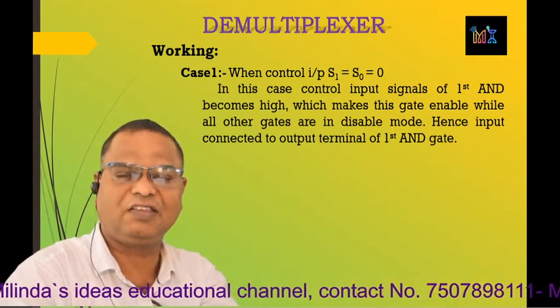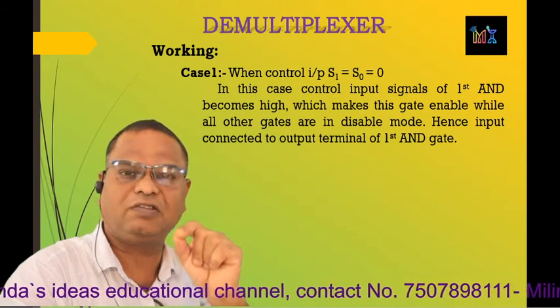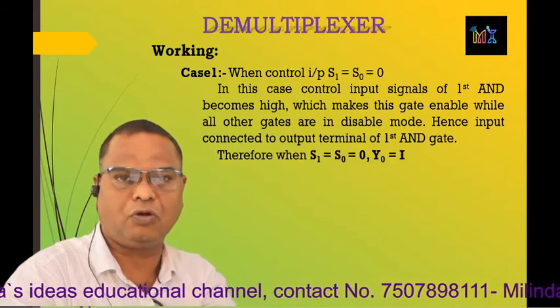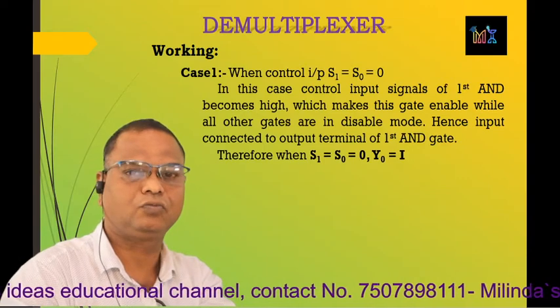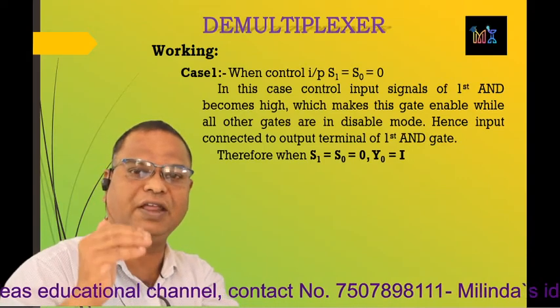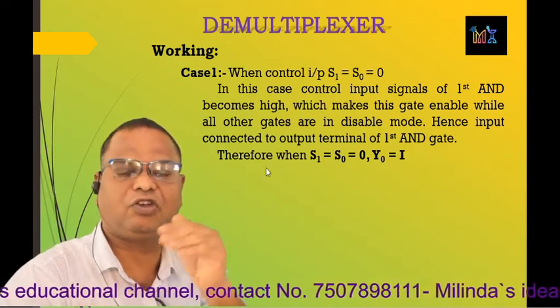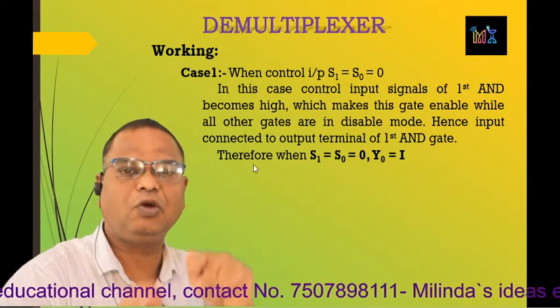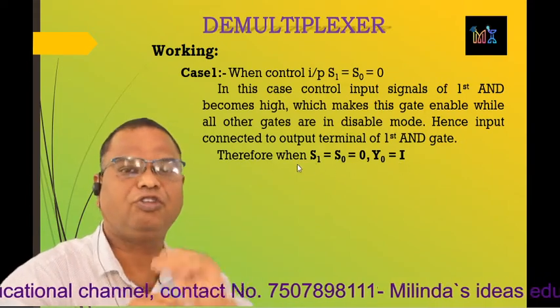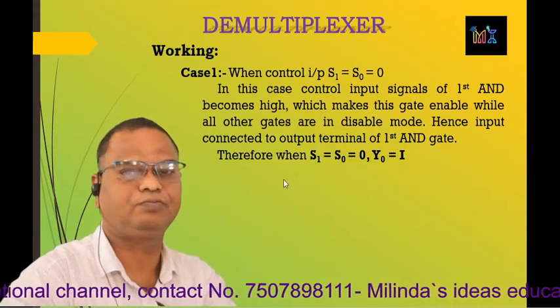So in this case, Y0 is equal to input or is equal to data. So that means when S1 is equal to S0 is equal to 0, Y0 is equal to I, or Y0 is equal to D, that is data.